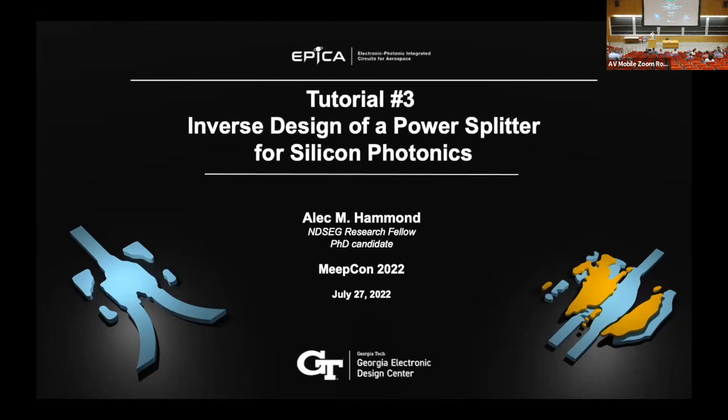You could take a series of ellipses that are parameterized by maybe various radii, for example, and you optimize those parameters, and it'll automatically take care of the material grid for you. And the cool thing is you can set beta equal to infinity. Everything is nice and binary, discontinuous, quote unquote, and it works really well.